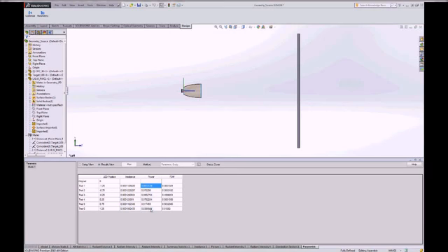And just to let you know, why does the power decrease for these other options? Well, when we move the LED back here, there's going to be some energy that goes off in space, if you will, doesn't make it into the reflector. Once we move the LED well inside of the reflector, the rays that are leaving the LED at a very high angle effectively miss a bounce. So they don't get totally constricted down to the plus and minus 30 degrees, so they're going to go off at a severe angle. Well, what does the irradiance look like?